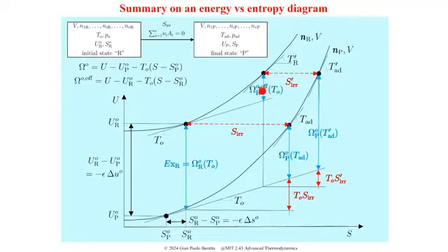Of course, preheating requires some availability, some available energy, this much. And this is the available energy of the heated reactants with respect to the reactants themselves. So I'm using the expression for the available energy. And then when I have obtained these products, of course at a higher temperature, see, T1 prime, they have this much available energy.